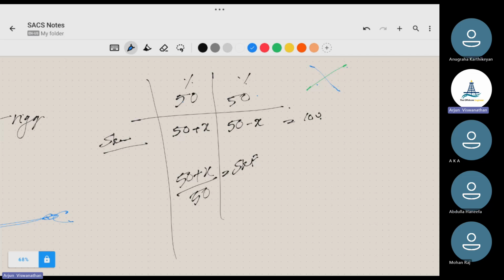Now we have a load redistribution happening due to the increase in length. One is taking more load and another one is taking less load, and this results in an unequal split. Instead of 50-50, one sling will take 50 plus X%. The total is 100%, so if one increase happens, a corresponding decrease will happen in the other sling as well, right?